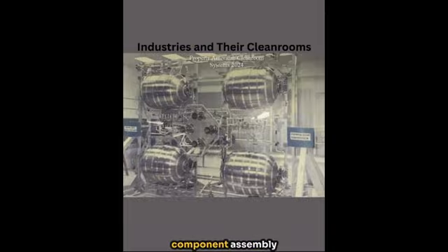Aerospace cleanrooms can be used for component assembly, such as rocket engines, GPS systems, and more, or systems assembly, such as satellites. In addition to cleanliness, electrostatic discharge is a significant concern. Static dissipative walls and flooring are a common feature of aerospace cleanrooms. System assembly aerospace cleanrooms typically have very high ceilings and doors to allow space for large satellites.